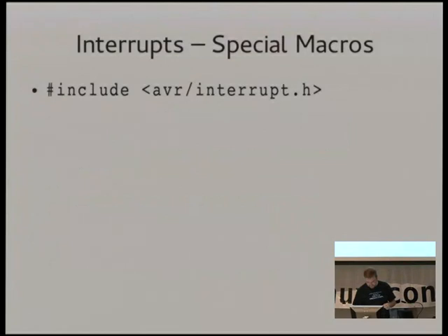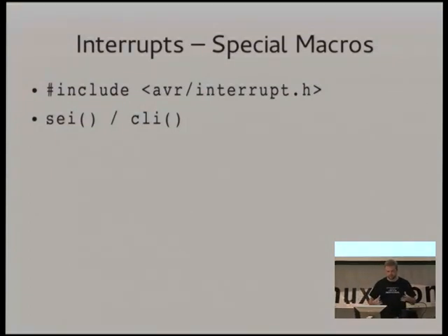So again, there's the set enable interrupts and the clear of interrupts. You need to put these around things that change the interrupts, because if you want to change the configuration of them, like turning them on and off, or changing what options you might have, the last thing you want is to have a timer overflow interrupt enabled, and then go and change the timer, and partway through you modifying that timer, it triggers an interrupt because the settings are half filled in.